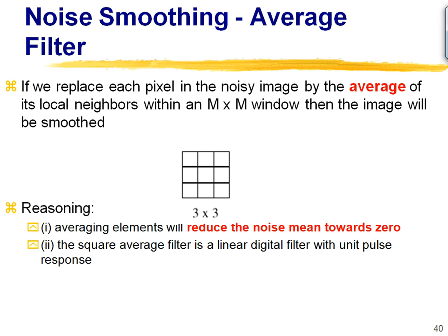Now, if I were to forget this and say, well, can I do this in space? Can I average 1,000,000 pixels in space and expect to get the benefit of noise reduction, smoothing of noise? Well, it makes sense, right? Whether the noise is sampled independently this way or this way, the noise is just this noise, right? I should get the same benefit. But of course, the problem is that across space, I can't expect my intensity to be constant, right? But what can I expect?